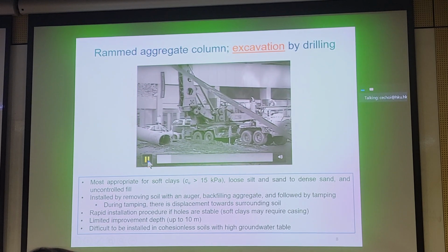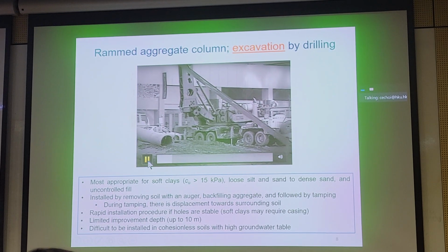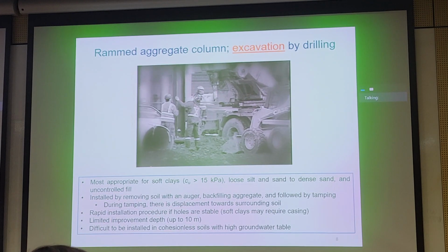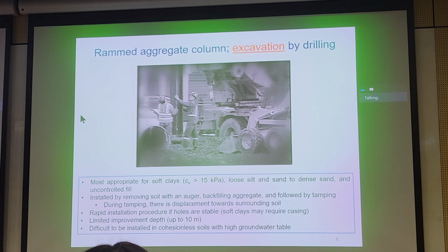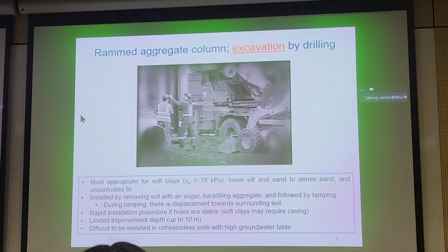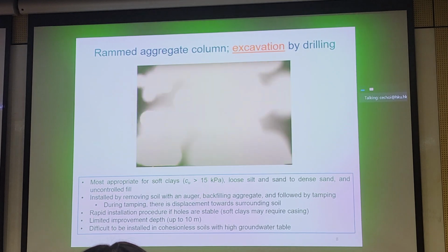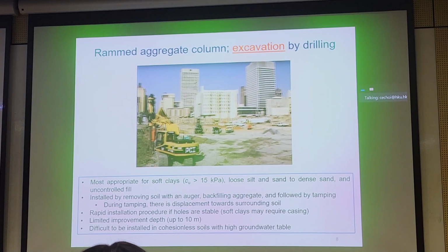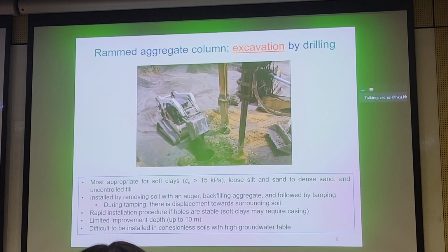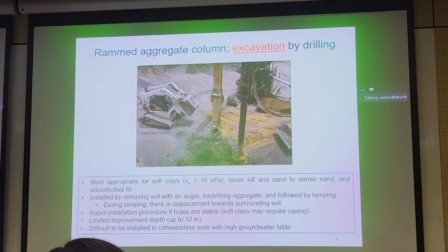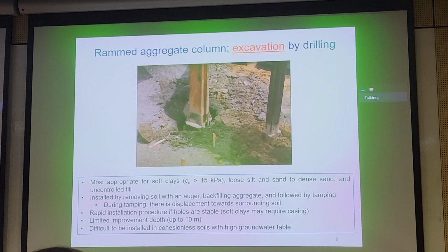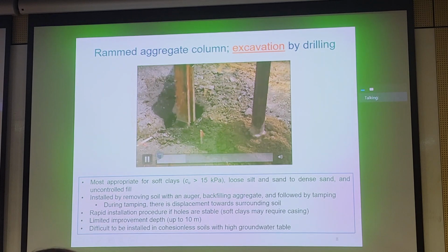For projects in which over-excavation was impractical, deep foundations such as driven piles were used instead, an expensive and environmentally insensitive process of driving concrete, steel, or wood into the ground. They basically said everything is bad. In the early 1990s, the Geopier Foundation Company developed rammed aggregate pier systems as an efficient and cost-effective alternative to historically costly and environmentally insensitive solutions.